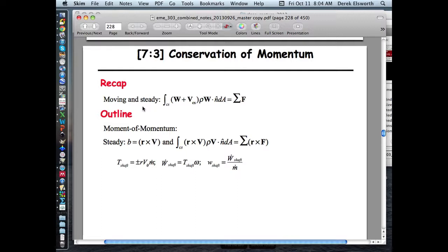Bernoulli is written kind of streamline-centric. Reynolds transport theorem for each of those, conservation of mass and conservation of momentum, allows us to look at arbitrarily shaped control volumes, and that's all. It involves an expression that looks like this. So this is perhaps the best expression to recall. Remember that we often write it just as a summation and throw away the integrals.